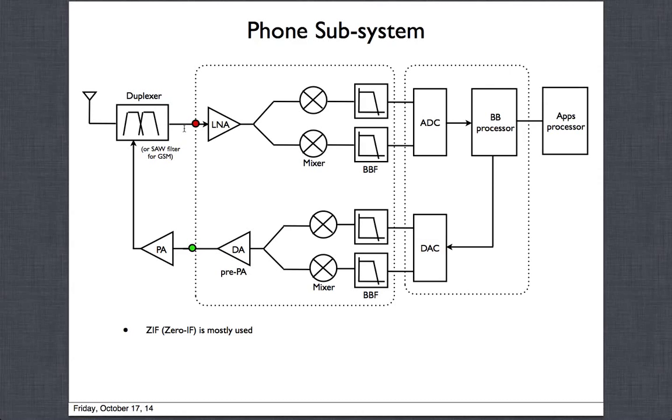Okay, so we are talking about mostly FDD type things. We're talking about systems like CDMA, WCDMA, LTE, HSPA, all those things. So as you can see, there looks like two filters. What the duplexer has is one filter for the transmit, and another filter for the receive.